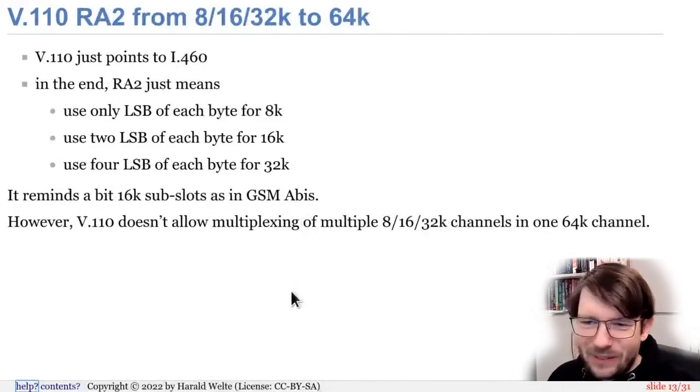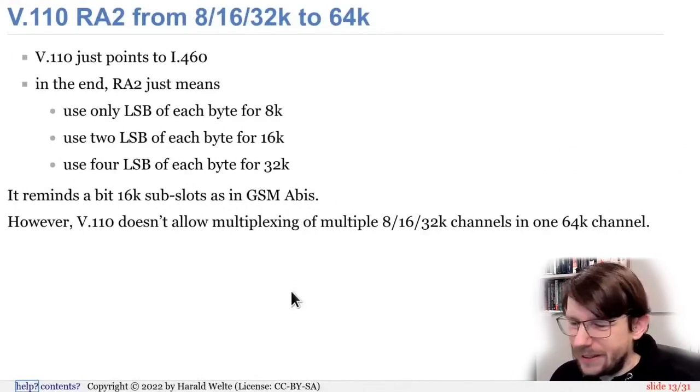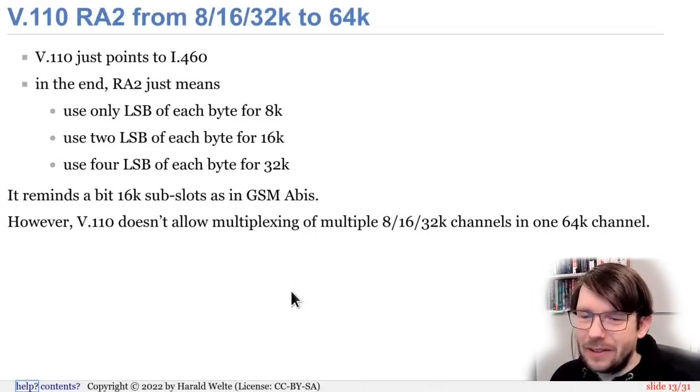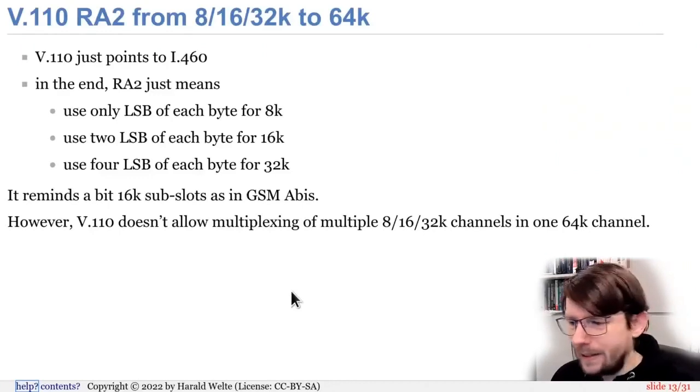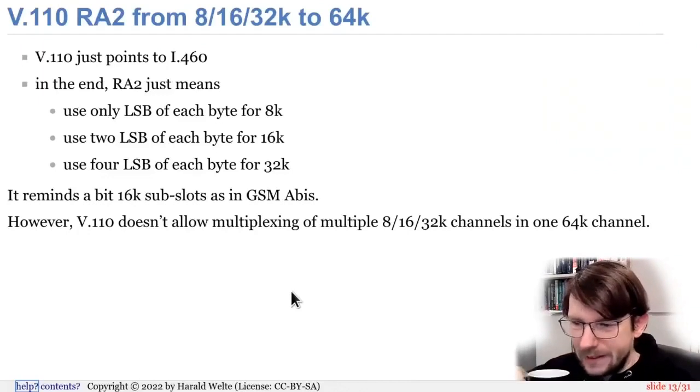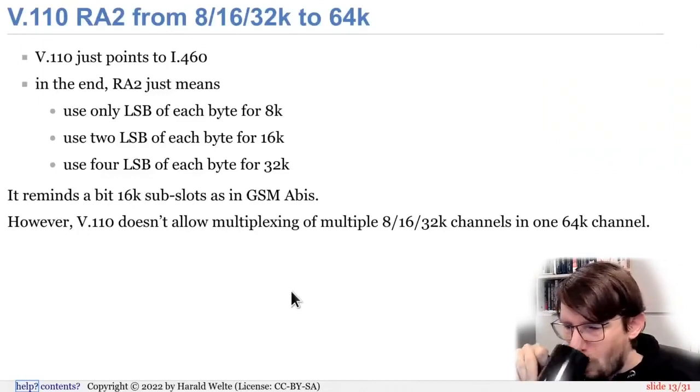that's an American problem, and V.110 is not used or cannot be used over restricted digital, so 56 kilobit ISDN. It's not possible. Christoph also says no, there's no provision for that whatsoever. So it is only possible in a true transparent 64 kilobit time slot.